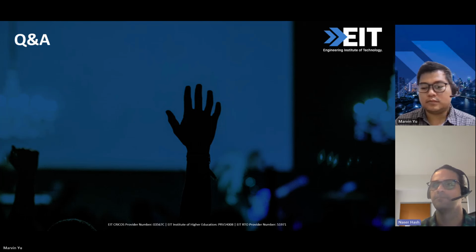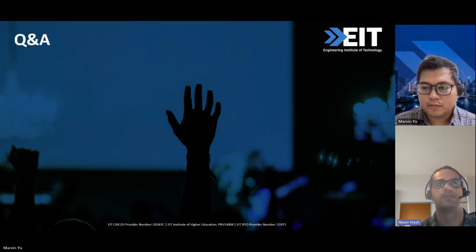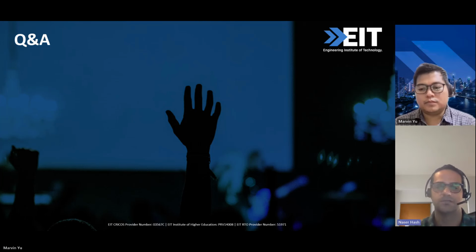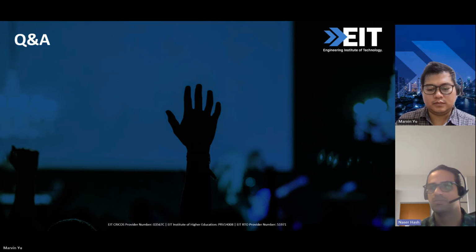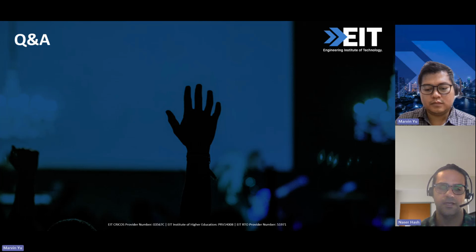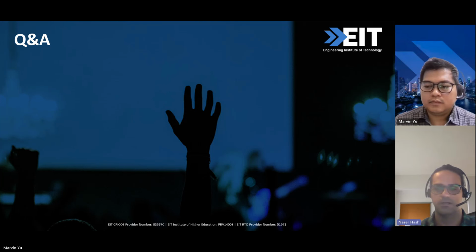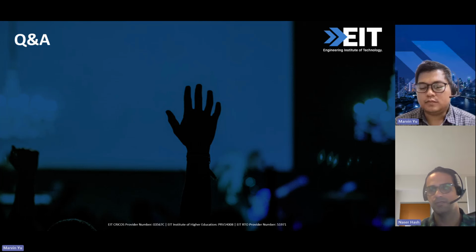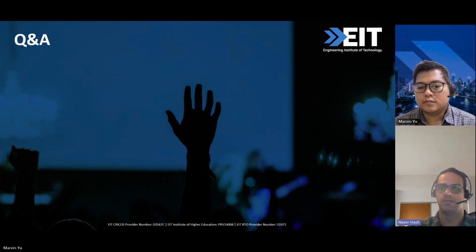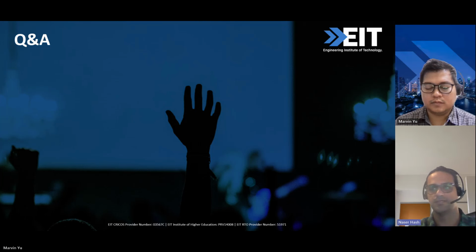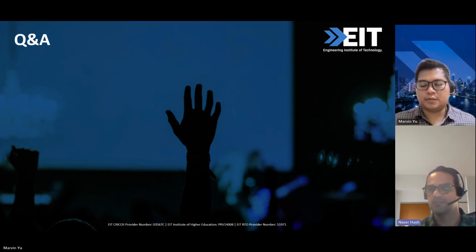There are so many. For example, one of them, I want to say there is a framework for health index calculation. One of them is DNO, distribution network operation, from the British network. Distribution and transmission network. They have created a framework for health index calculation and probability of failure calculation. This is just a basic mathematics approach, a simple way of calculating the health index. But if you want to go to a higher level, more advanced, then the simple health index doesn't help, because it's just a simple calculation.